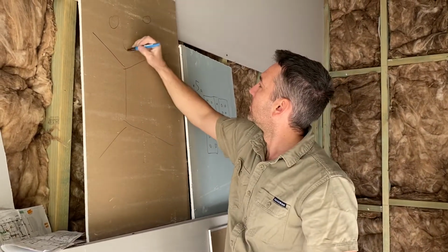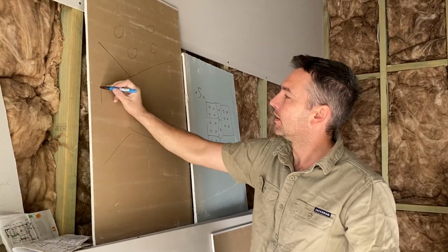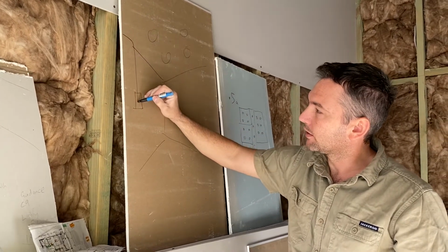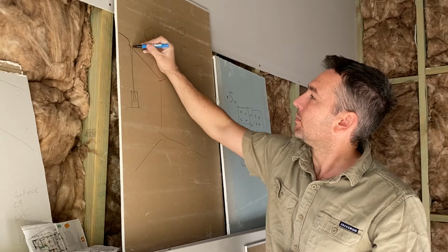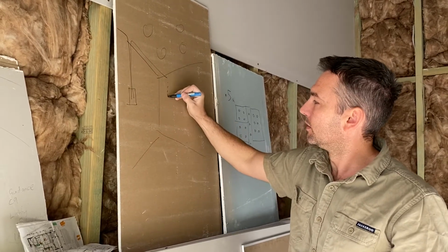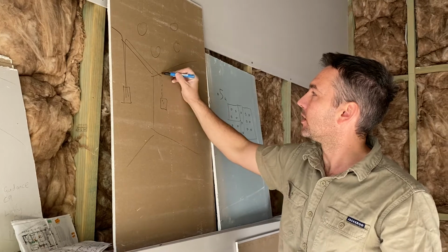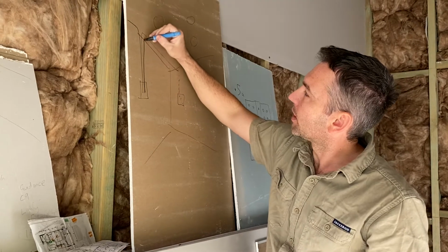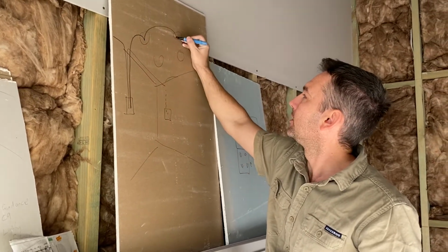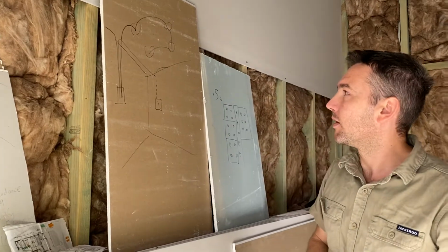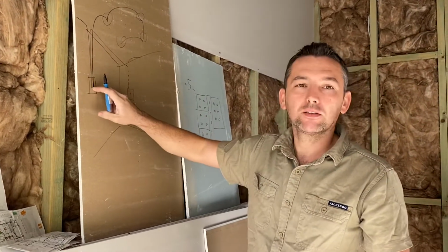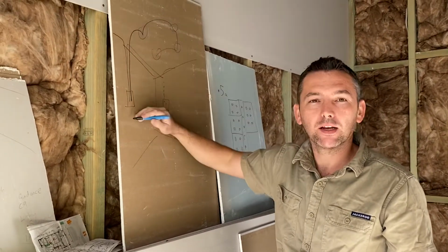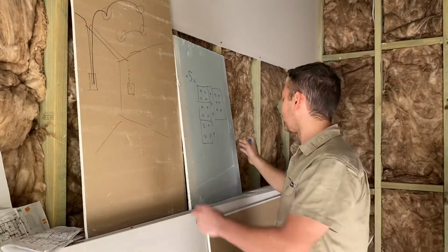Say you've got your 4 downlights up on the ceiling, and your light switch. You can run your 1.5mm cable down the wall to provide some power, come back up the wall, go off to the next room and power the next light switch, and so on. Then at your switch, you have another 1.5mm cable that comes up, hits the light fitting and goes off that way. That's powering the switch and only using 1.5mm cable. You use a little bit more cable going up and down the wall, but that's one method of choice.